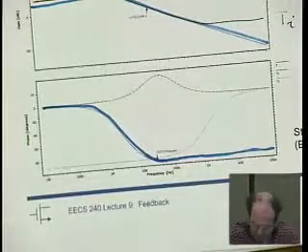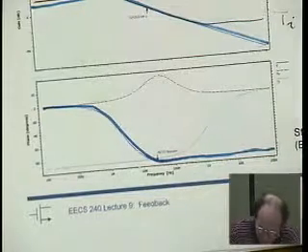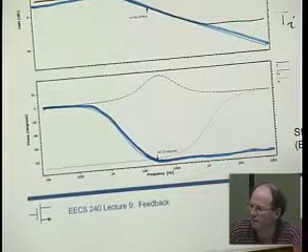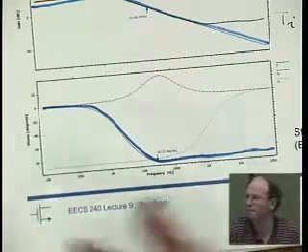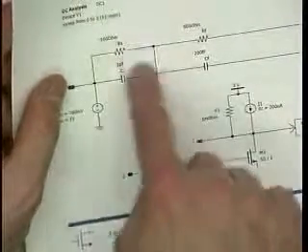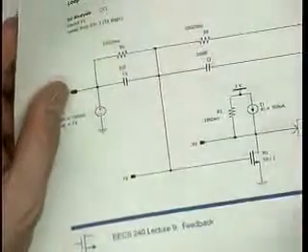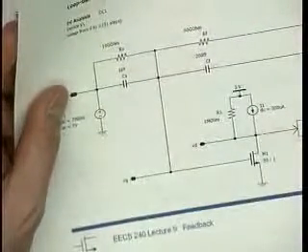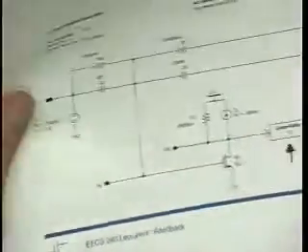But now back to here. I actually have an idea why we get only 88 degrees of phase margin. There has got to be another pole here. Well, I mean, the other pole's here. There is another node, and of course I've put some resistance here. SPICE insists on me doing that, and so I get a degree or two of phase lag. That's what it must be. Okay.